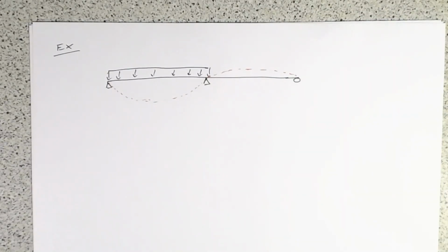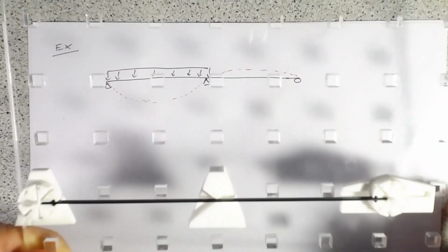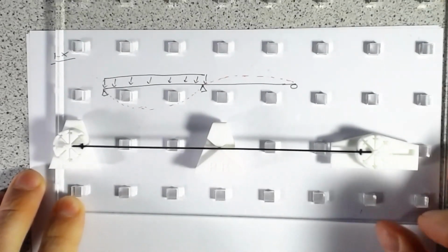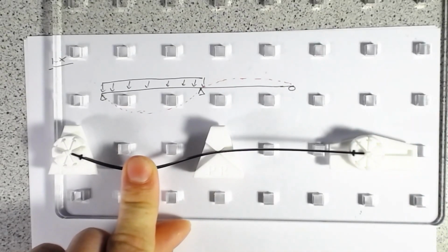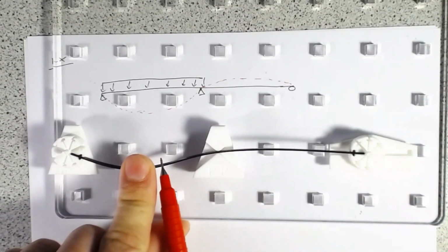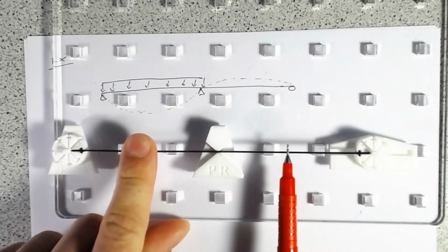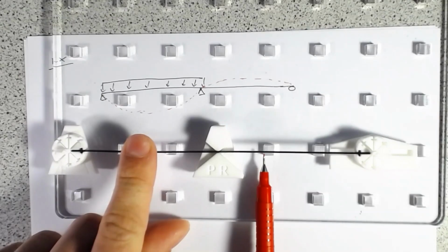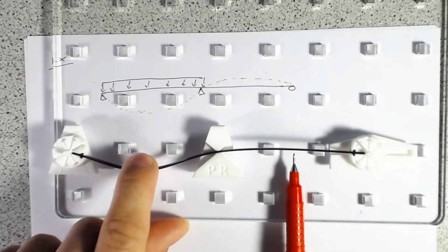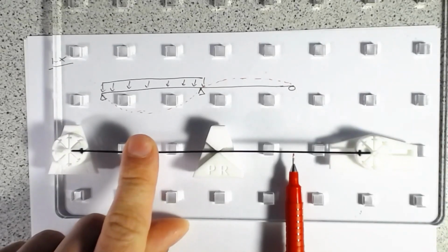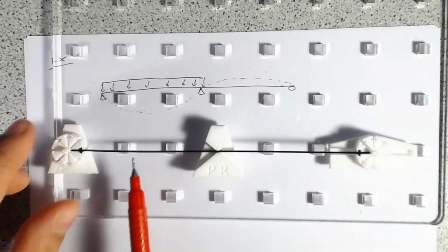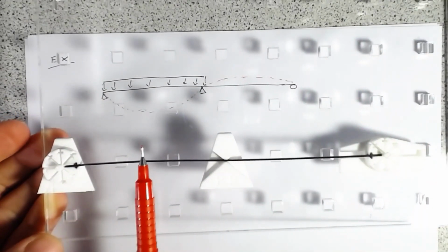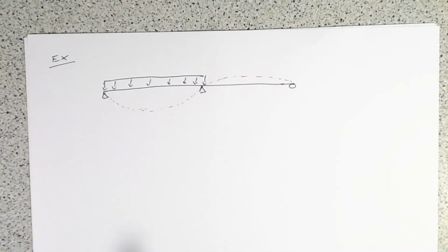something like that. And just like with the point load, it's hard for me to put a UDL on this, but we know that the span which has the load applied is going to have much higher deflections than the span over here. So if I just put my pen right here at the end, you can see it does move up, ever so slightly. The loaded span has much higher deflection, so we're going to have a higher moment. And so you can think of that as our relative moments there.